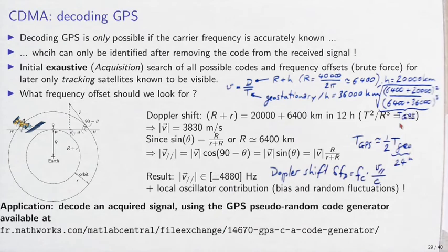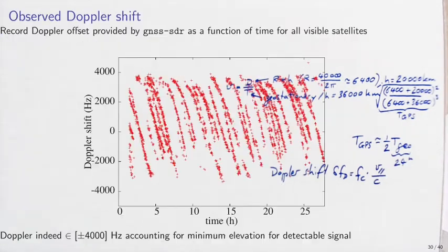So what we would like to address is how to distribute this plus or minus 5 kilohertz. What is the frequency step within the plus or minus 5 kilohertz? If we want to convince ourselves of the validity of the calculation, we can check experimentally what are the actual Doppler shifts of measured carrier frequencies.